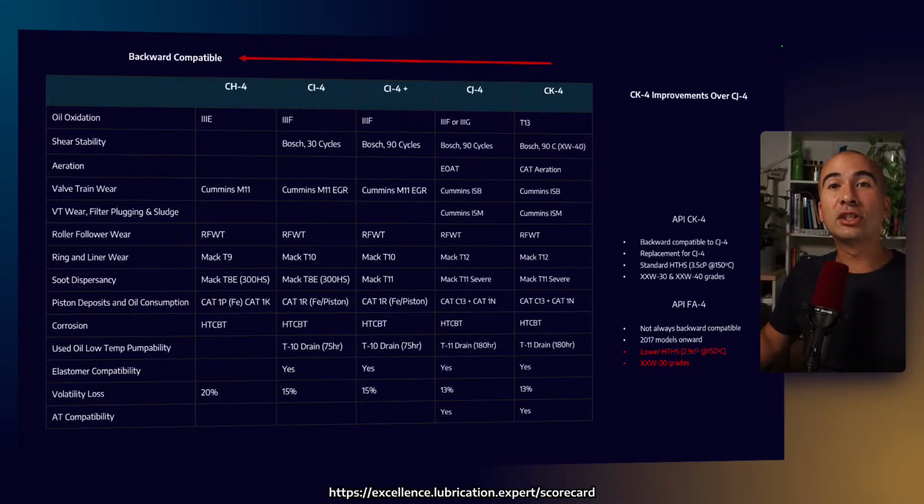All right. When selecting engine oils, there are a whole bunch of different standards. The API, for example, that you would have heard: API CK-4, API SN, API SP. The easiest way to remember which one is applicable to which: S stands for spark ignition, C stands for compression ignition. So one is for basically petrol engines, one's for diesel engines. Now, in actual fact, that's not what it stands for. The S stands for service and the C stands for commercial. So actually the API is basically dividing it up between light duty and heavy duty engines.